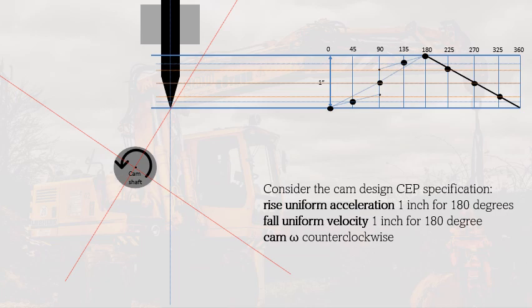So this is now our new axis. It means that if we're going to rotate this follower into this line, we can draw the cam profile. How do we do that? It will be easier by drawing also the concentric circle that would pass through this horizontal line intersection with this axis, but this time our circle should be concentric with respect to the new xy plane.